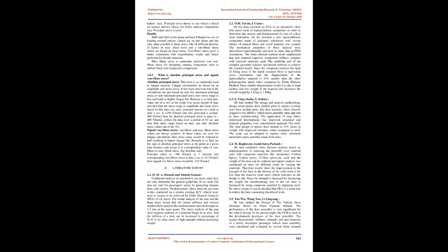subjected to multiaxial loading, normal and shear together, the nature of the stress-strain curve will not be the same, the graph will be different. It indicates that for different combinations of loading, Fx, Fy, Fz, Mx, My, Mz, different graphs should be referred to. Therefore it is not practical to conduct so many tests. Then how can components be designed when subjected to multiaxial loading using available test data for uniaxial loading? It is achieved via theories of failure, which give us the equivalent maximum normal or maximum shear stress or energy of the component subjected to multiaxial loading.